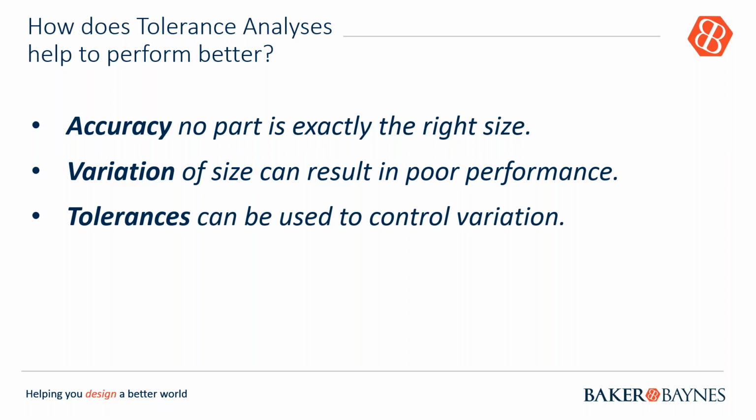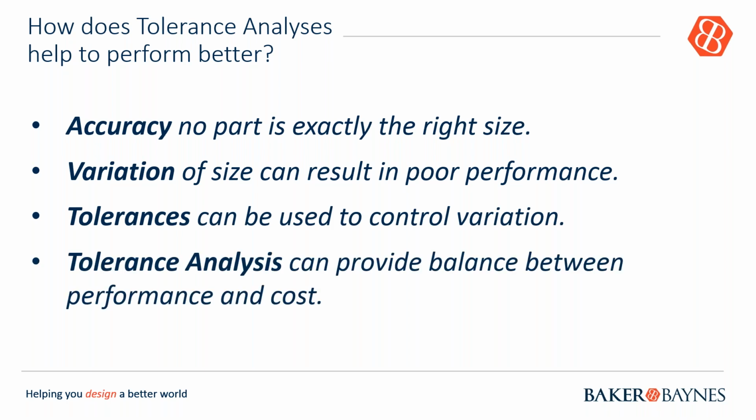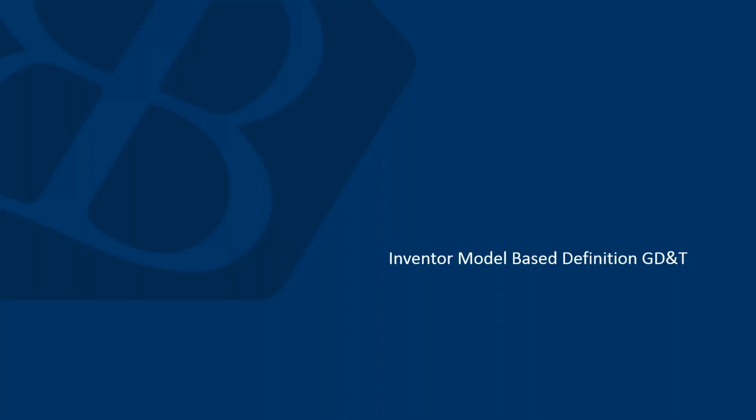Variations in size can be limited using tolerances, but the more accurate the tolerance, the higher the cost of the component becomes. And finally, tolerance analysis can allow us to find the best comparison between performance and cost. This is ideally what it is assisting us to do.